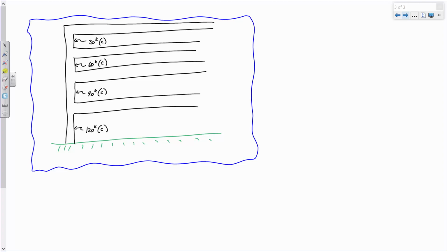See what I mean? Really easy for that to happen. Does that make sense? So I just wanted you to see how we can take a floor loading and break it down into items that make sense. So if I'm in column design, design that column to withstand 120 kips. If I'm in beam design, design that beam to be a 30-foot long beam to withstand whatever 200 pounds per foot, right? That's sort of where we're starting with this.